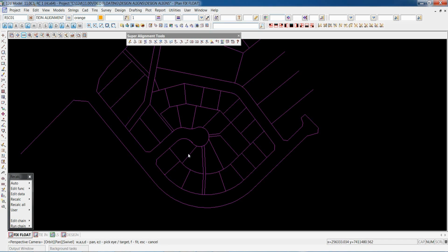This resulted in alignment designs that could take into account horizontal constraints, such as offsets from straights, like property boundaries, offsets from arcs that could have passed through an existing road centerline, arcs that pass through a point where the radius is unknown, compound and reverse curves, 2-centered and 3-centered curves, straights and arcs that could extend through a point or at a set distance from the previous geometry part. In the more advanced road and rail design element method, arc-to-arc and back-to-back transitions between arcs and straights were expanded.